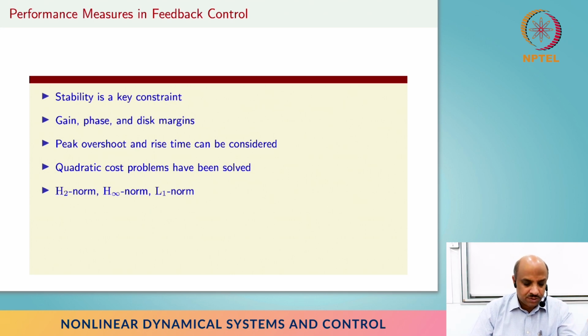So it measures basically the system response to some kind of white noise in a particular fashion. So we can minimize the H2 norm of the closed loop so that we know that it's robust with respect to white noise, right? Similarly, H infinity norm is also something to do with response to a disturbance of a different kind. The disturbance in fact need not be stochastic in nature. It could be simply bounded in a square sense, right?